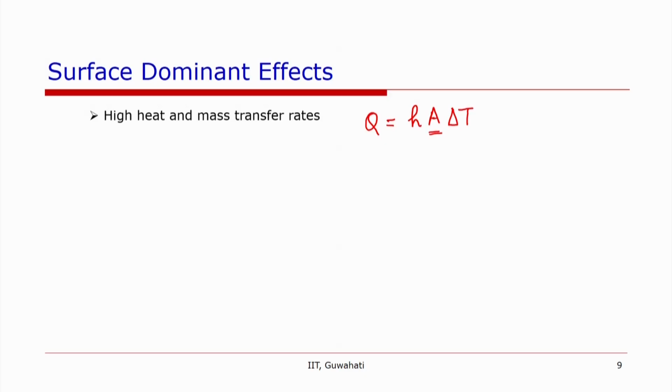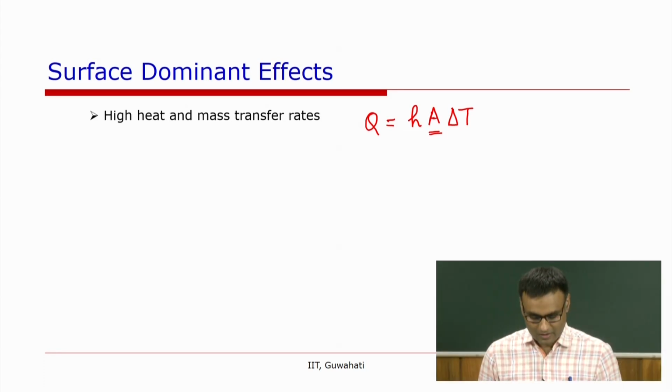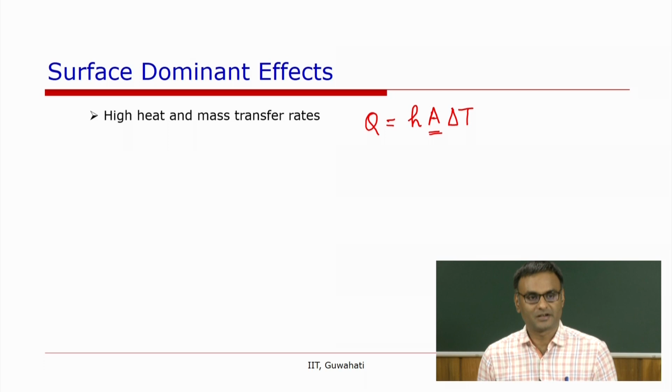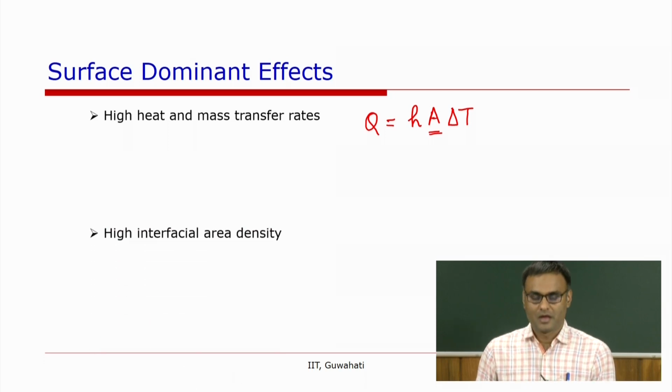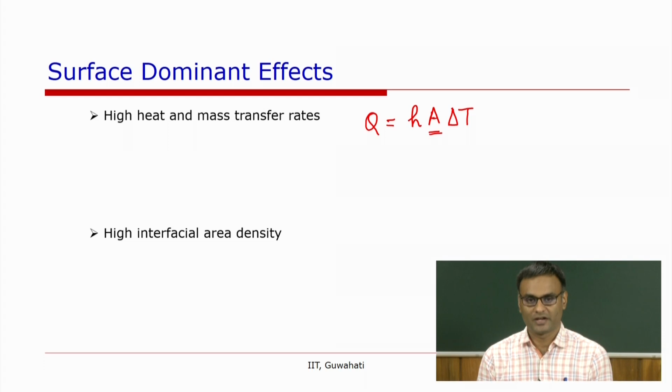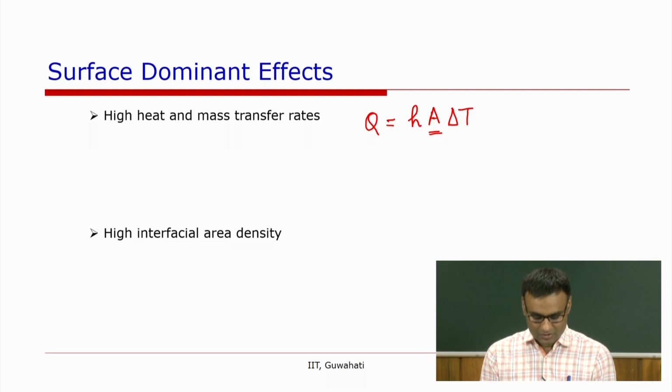That is the reason there are a number of heat transfer applications of microchannels, for example, in electronics cooling. In two-phase or multi-phase flows, say gas-liquid flow, the interfacial area one can achieve in a microchannel is 2 or 3 orders of magnitude larger than in larger channels.